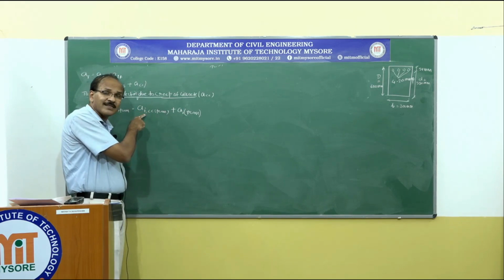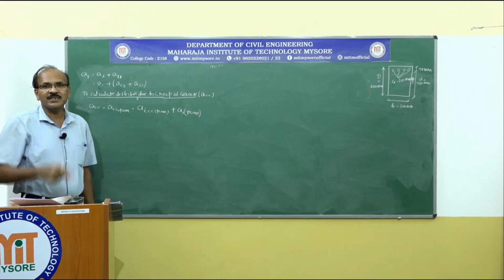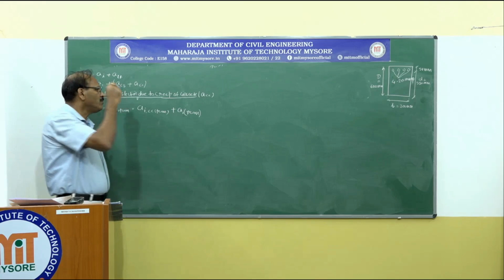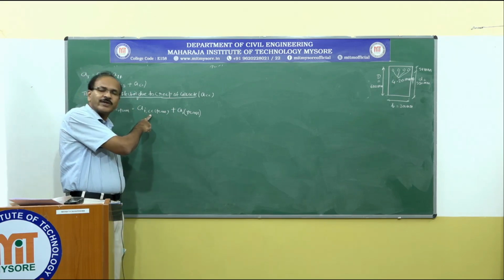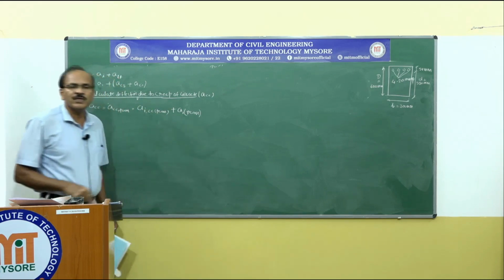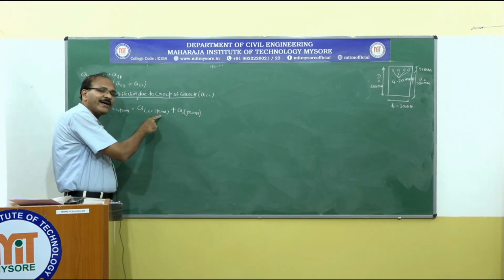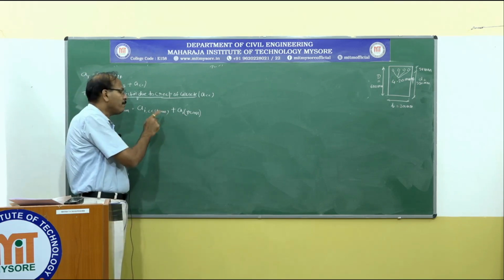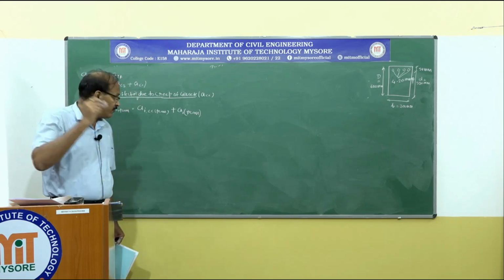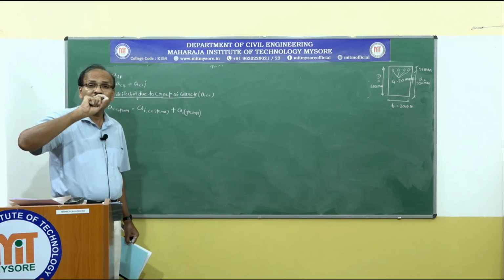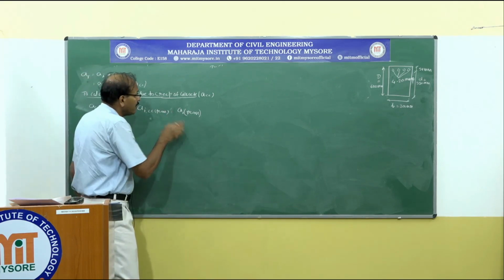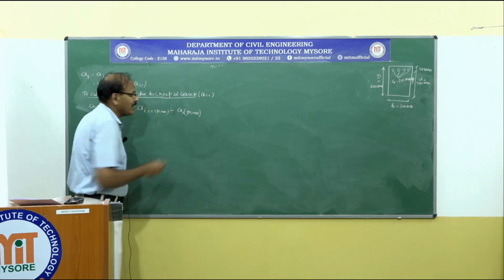Total deflection is nothing but the immediate deflection plus long-term deflection due to creep of concrete. Those two things we are going to get due to permanent load, and not the live load, we have to take out the live load. And this is not plus, this is minus.